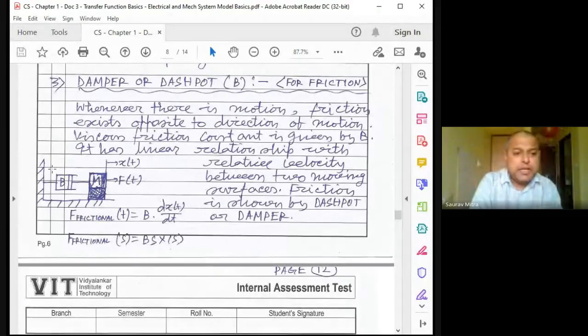Okay, so this is the dashpot, and we are giving the frictional force f(t) to open it, and see how it closes. As soon as we push it, we give some force and open that door, but the closure of that piston flows through a resistance. The resistance occurs because within this piston there is a viscous fluid. So this piston enters the fluid, and very slowly it presses the viscous fluid or air, and then comes to the ending position.